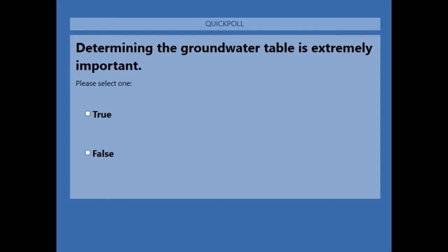The number of borings for water and sewer installation. That's kind of a tough one. It generally depends on what we think is out there, but we typically do a boring for every 500 to 1,000 lineal feet. But I have done some where we've been profiling the bedrock, where we've actually done them about every 100 feet in various areas, especially if bedrock is shallow.